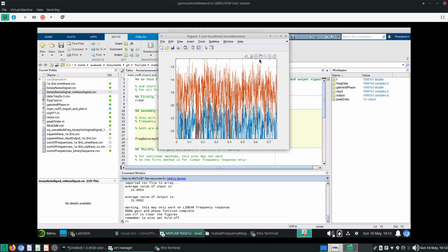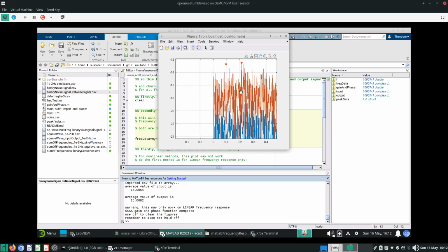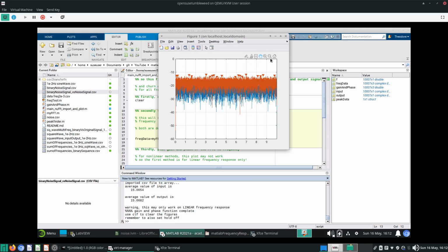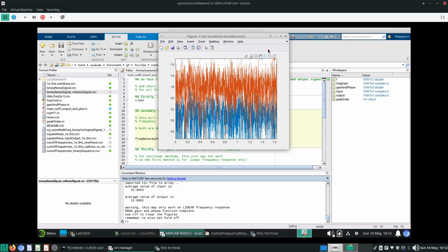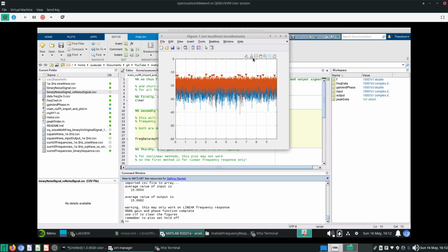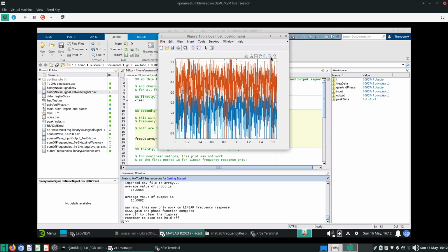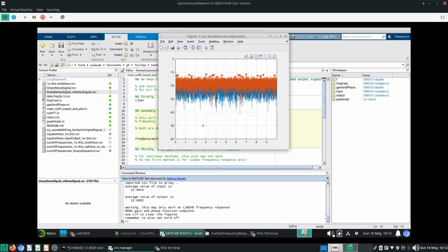We can see that the input signals are basically a mixture of frequencies all over the spectrum, and you can see it's a nice, even sort of spread of frequencies. Now, if that's what you want to use to test your signals and get a frequency response, by all means. It is a very nice signal if your system is linear time invariant. And as long as your signal is much greater than the background noise, I think you should not have a problem.